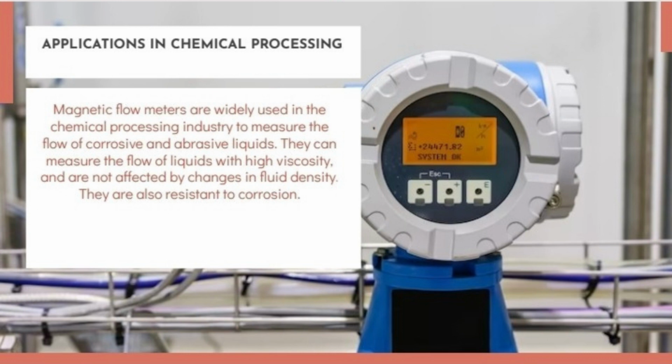A modern design of magnetic flow meter is the one which can be inserted into the line through a coupling. It consists of electrodes mounted on each side of the probe, and the magnetic coil is also integral to the probe. The probe can be mounted on pipes of diameter 152.4 millimeter and above, and can easily be mounted for open channel flow.